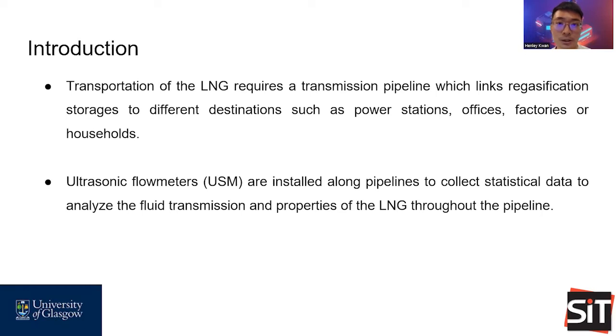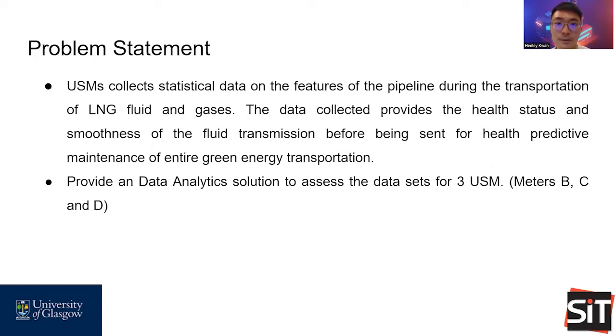So LNG is actually transported throughout the pipeline. Throughout the pipelines, there are ultrasonic flow meters, USM for short, to collect statistical data to analyze the fluid transmission and properties of the LNG through the pipeline. So the problem statement is that the data collected needs to provide the health status and smoothness of the fluid transmission before being sent for health predictive maintenance of the entire green energy transportation.